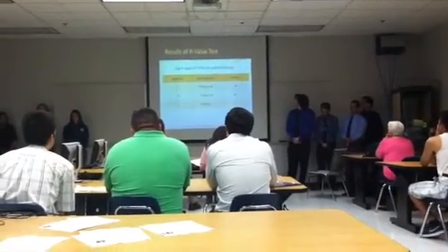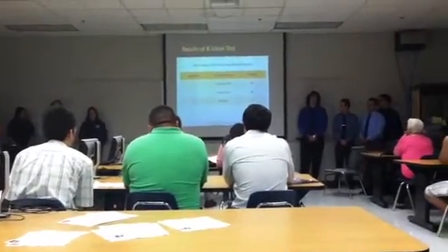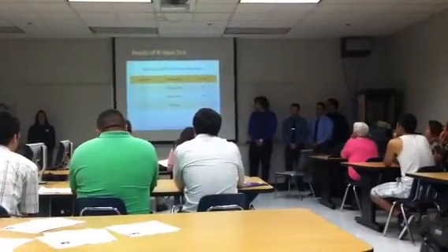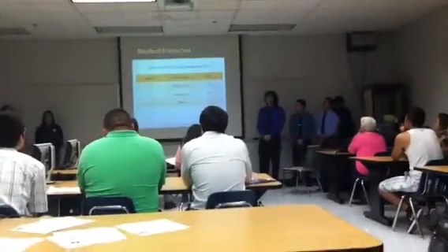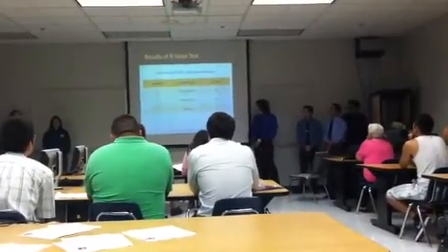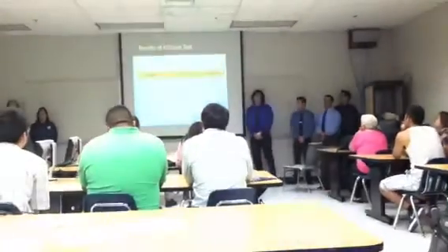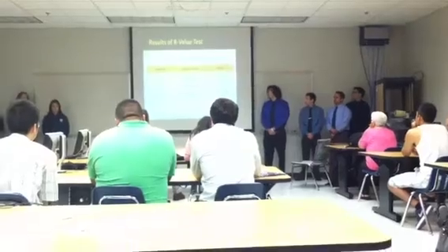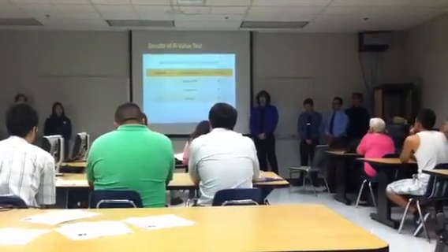Here we have a list of our R values. When you have an R value of 30 or greater, it becomes adequate for pavement design. And as you can see, all our locations are adequate, with our first location, parking lot M, having the lowest R value. That's the value we picked for our design basis, since that location can take the least amount of stress.